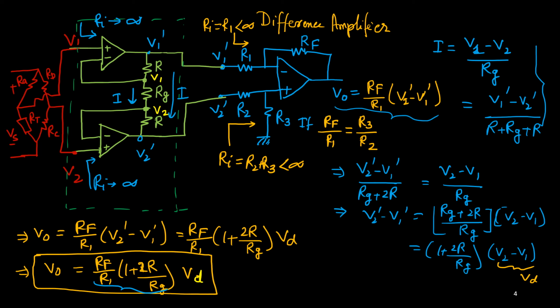So every time it is very difficult to adjust those four values. In this case we can use one IC where the elements R1, Rf, R2, R3 are made in IC form, and externally we can connect one RG. So just varying RG, we can vary the gain factor.